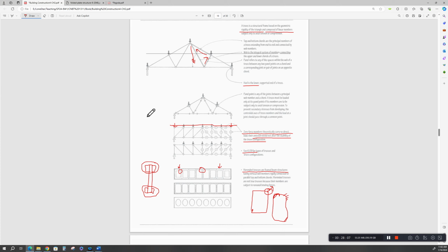They found that out with Liberty ships during World War II. They were making them super cheap and quickly. So they would just have these square hatches in the hull. And when we got out in the rough seas, they found that the surface decking cracked along these lines. And the same way with concrete. You have square openings in concrete, you got to watch for cracking. And so the easiest thing to do is to put radius in your concrete formwork or an open hole. Okay? That way these stress concentrations in the corner are evenly distributed and not concentrated just on a point. Does that make sense? Okay.